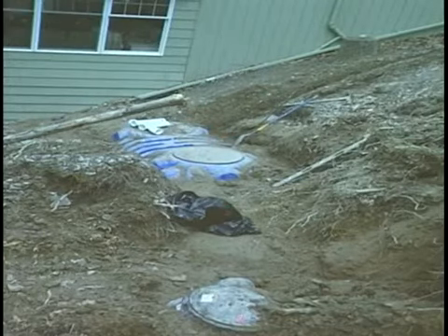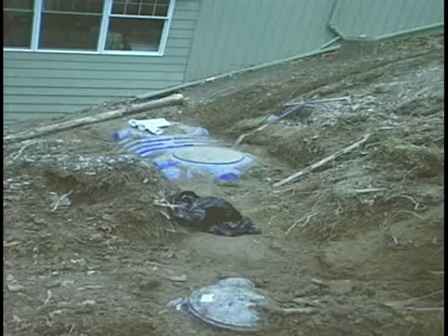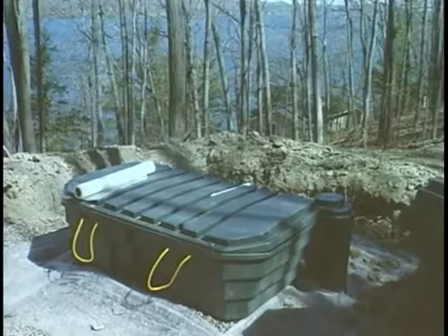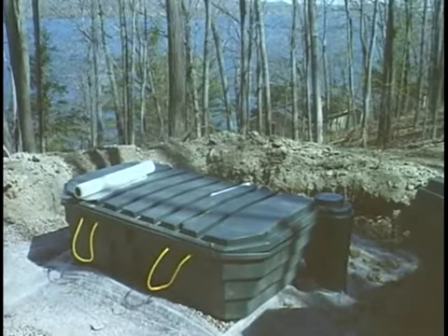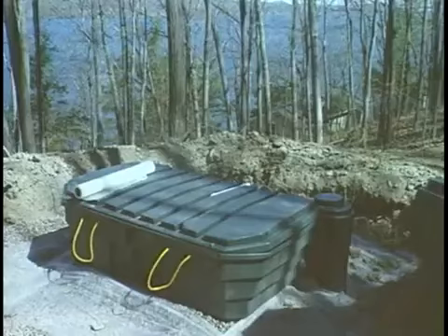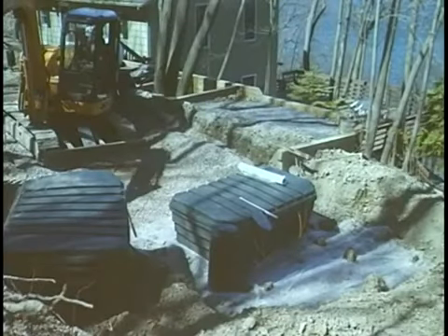Here's the pump tank, a PVC pump tank. Again, we couldn't get a concrete one in, but we're up above groundwater, so it's not going to float. We're way up on the embankment on the lake. It pumps over to 3 peat moss modules. And if you look at the design of the peat moss modules, it's usually 1 module per bedroom. So this is the installation of this system going in.